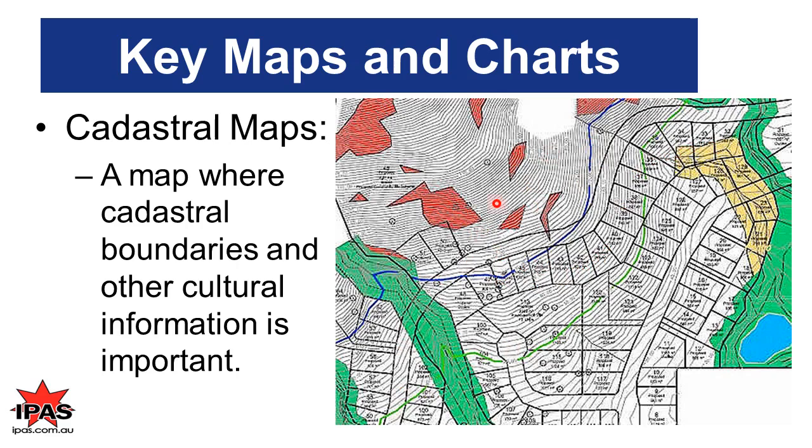You can see the contour lines there, and as I said before, contour lines that are close together means the terrain is steep. But in this case, I would expect that not to be such steep terrain, especially if they are residential blocks. So I would suggest that the contour lines here are representative of close contour intervals, maybe 10 centimeter intervals or 50 centimeter intervals.